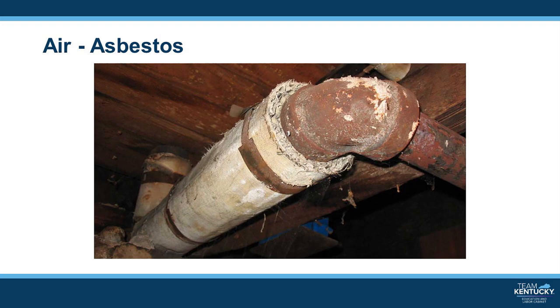Do not clean it up yourself. Do not remove it yourself. If you are working in an area with suspected asbestos, avoid accidentally bumping it or breaking it. If it needs to be removed in order to access the part that you need to weld, it should be done only by someone who is trained and equipped to remove it safely.